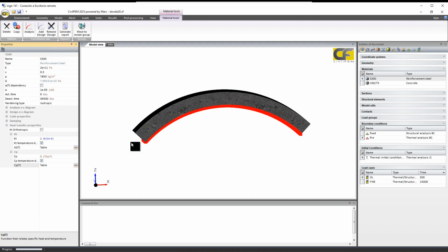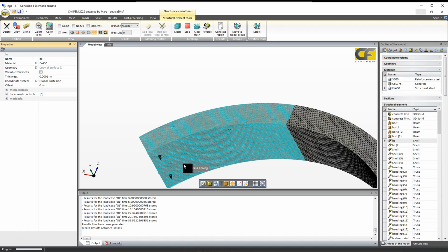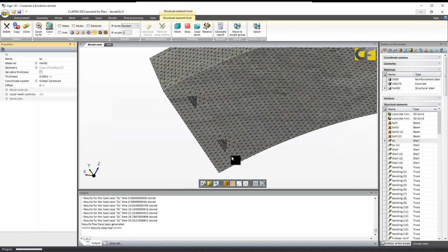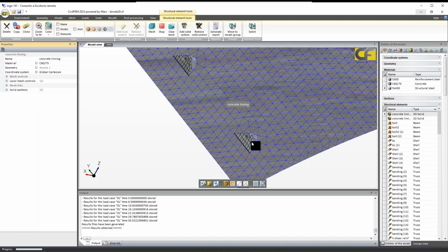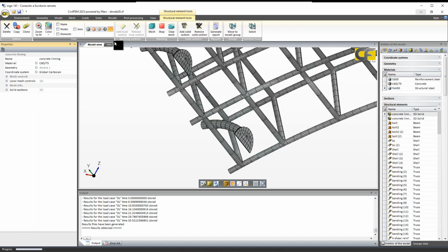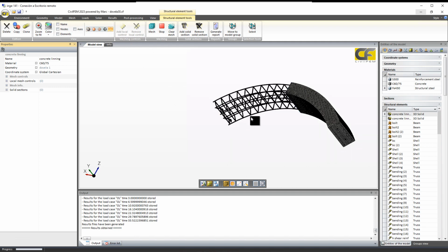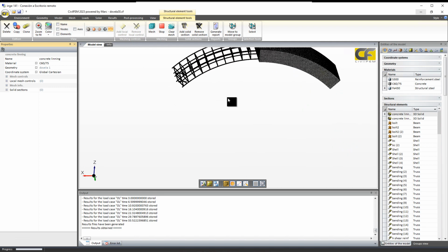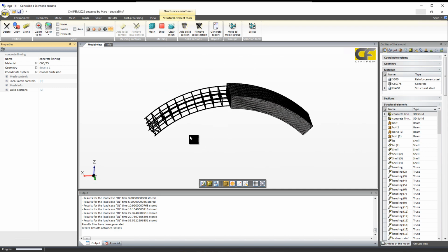And another intermediate result was with another model. Here we have the other model that is an elastic connection. This elastic connection is through these bolts that are connected here through these holes. So these bolts were connected to the rest. Also here we can see the reinforcement groups, bending and shear reinforcement groups. So we have applied 5 minutes of loading boundary conditions.